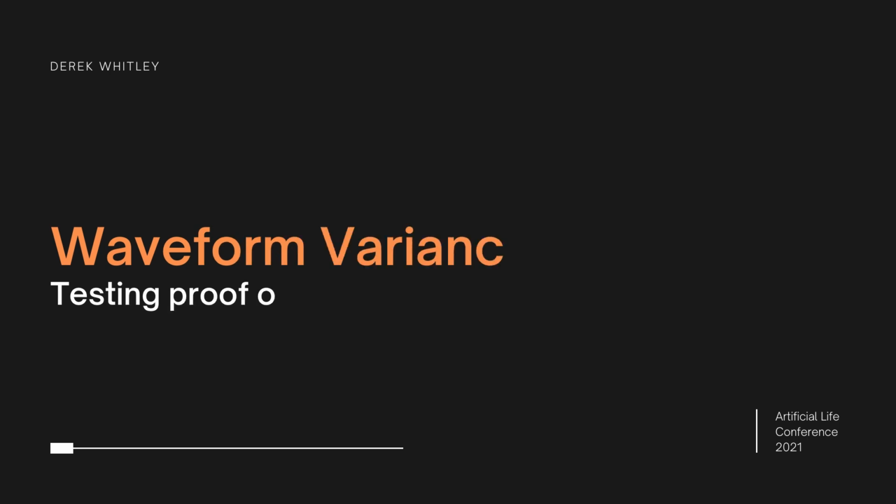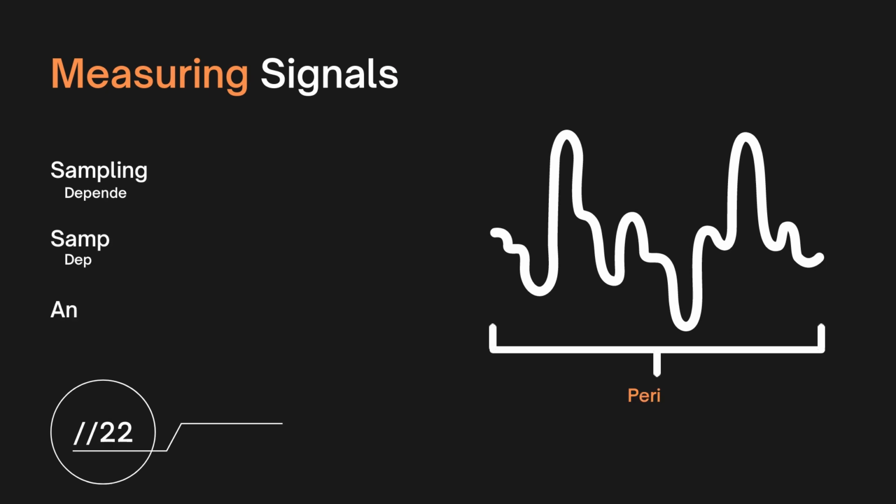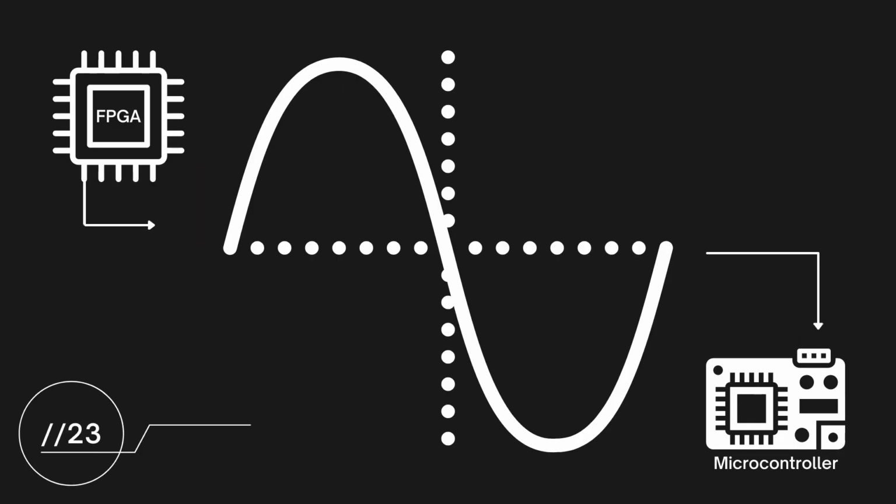Doing so, we wanted to take the simplest approach to analog circuit evolution as possible. This first meant evaluating the components of the signal we would be receiving to determine what we wanted to manipulate. Knowing that the signal produced from the FPGA is a continuous wave and that the microcontroller can only capture a sampled portion of it, our options for waveform manipulation are limited to the microcontroller's sampling capacity.